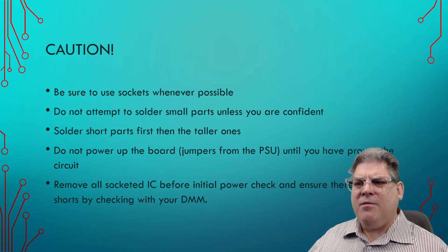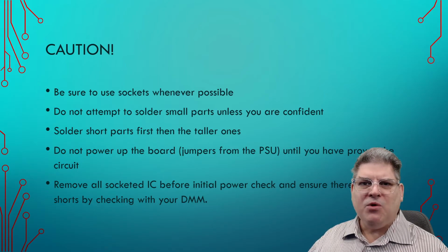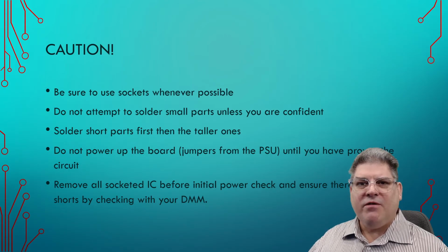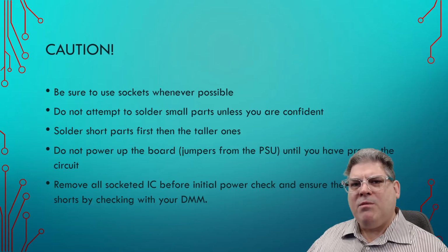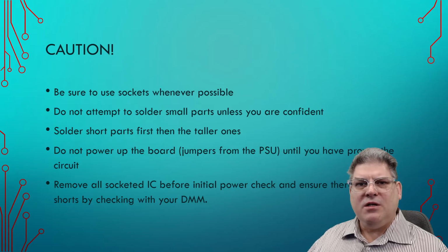So keep that in mind. Don't start by soldering the most complicated part on your circuit board. Start off with the simple stuff and move on from there. Also remember, solder the shortest parts when possible.